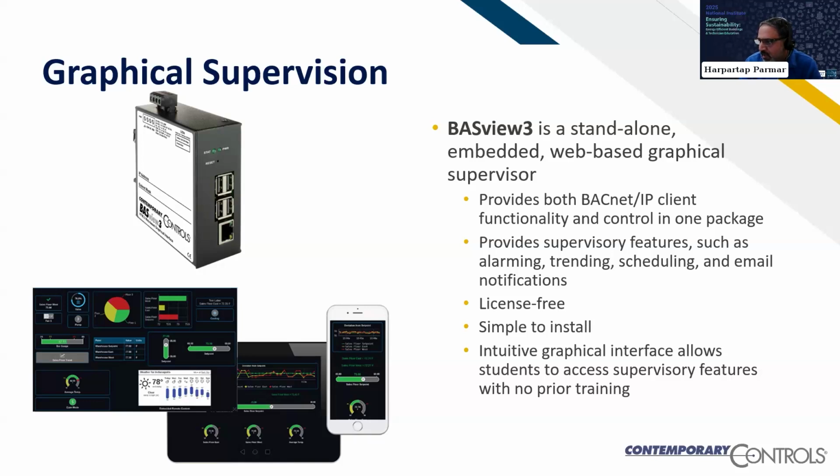You can configure it all through a simple web browser, and it gives you supervisory features and functions such as alarming, trending, and schedules. You can also use Gmail to set up email alerts and notifications. You also get BACnet IP client functionality in that, and it also supports Modbus TCP.